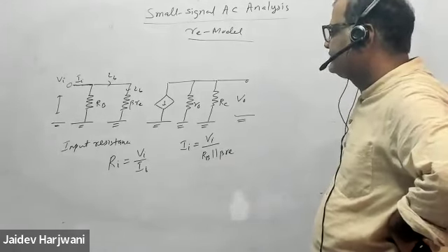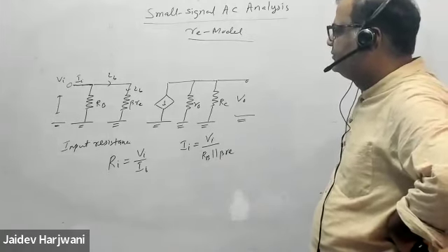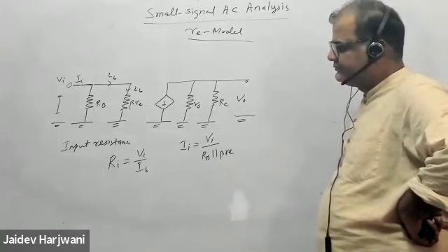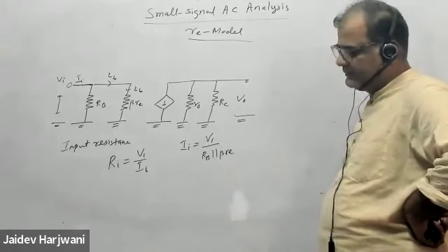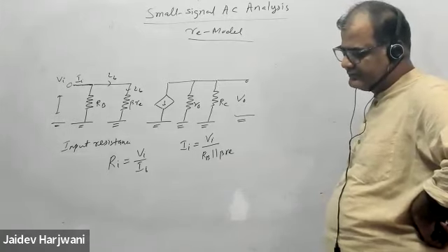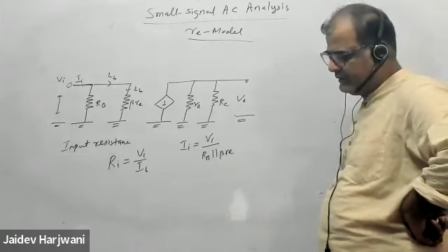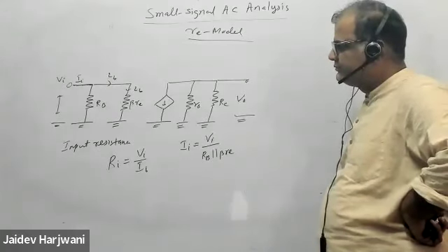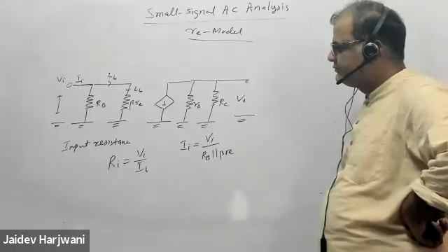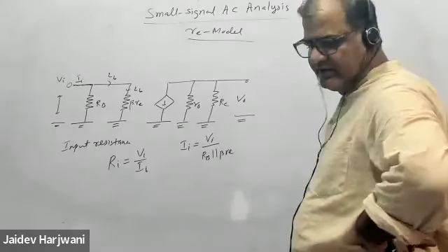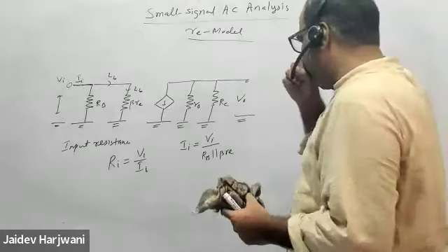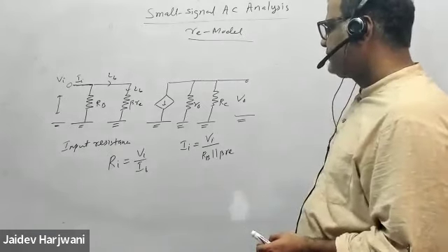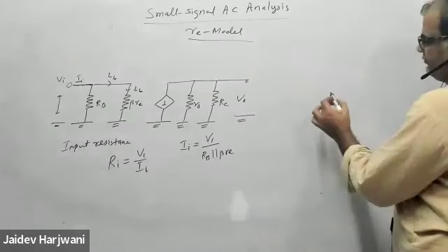And one more thing. Okay, sir, tell me. I have a question. In DC biasing cases, when we solve the KVL system, we just consider RB and RE in series combination. But here we are taking them in parallel combination. Where is RE? RE means beta RE, that is the resistance across the transistor. Yes, right.